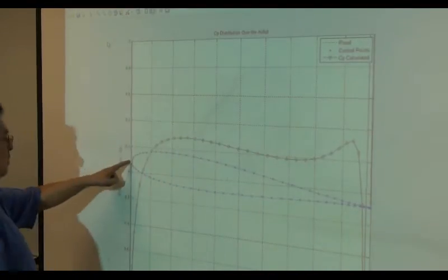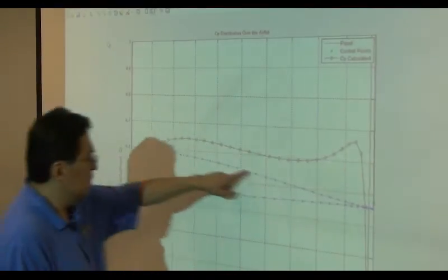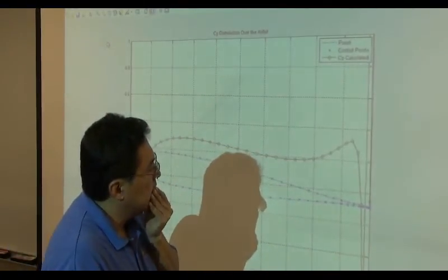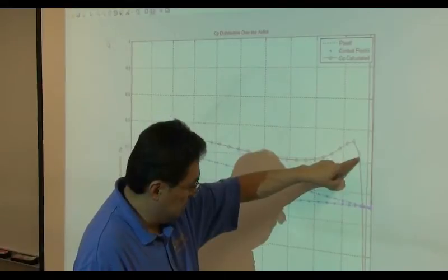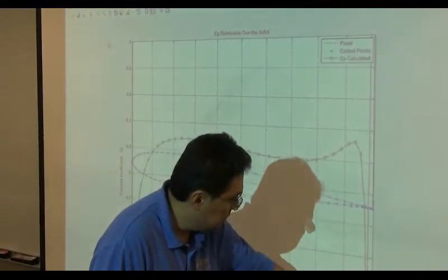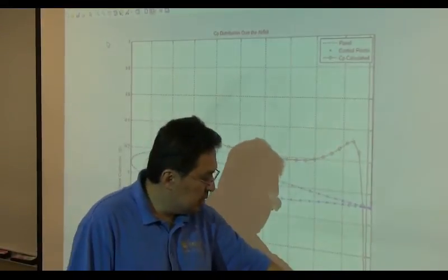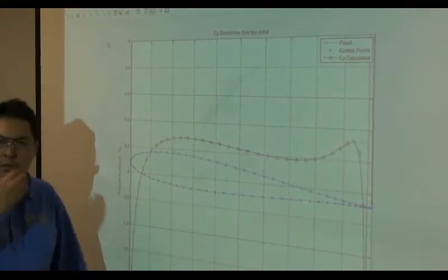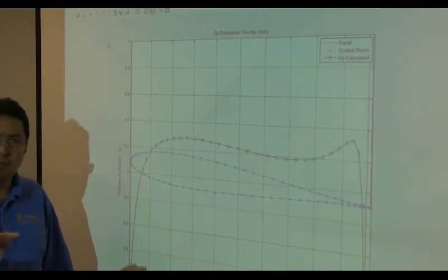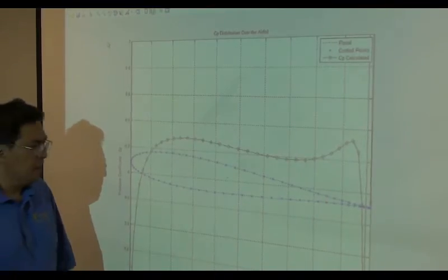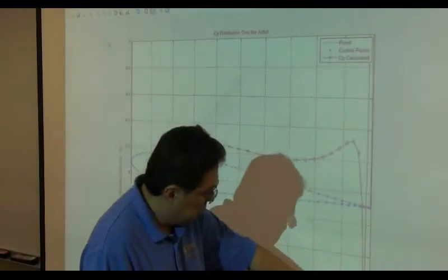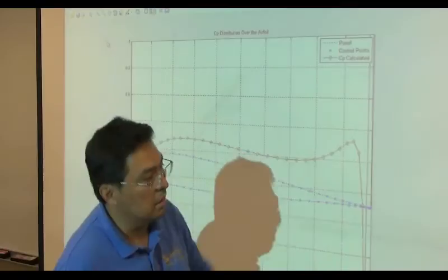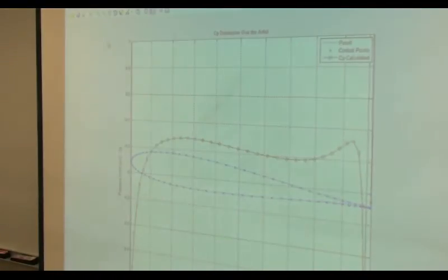I'm talking about only the upper surface pressure coefficient. Right here, the pressure really increased, so that it is almost close to CP equal to 1. So what's CP equal to 1? What CP equal to 1 really is, is a stagnation point, is it? Am I going to create a stagnation point here? What's going on? Well, all right. This is what's going on.